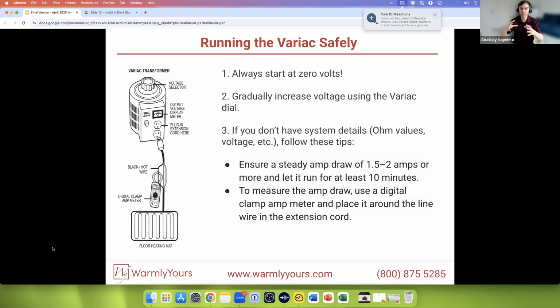That tells you that something is heating up, and in our case, that's a short. We know there is a short that will slowly heat up. So keep in mind, inside your system there are 2 heating wires and there's a ground, so there's like 3 things running inside there. If you're heating from your ground to one of your wires, that area probably won't get as hot as it normally would, because you're only heating one of the wires in the twin assembly. So that's what you're going to be looking for.